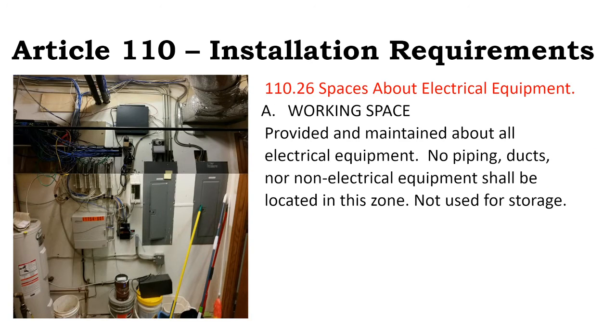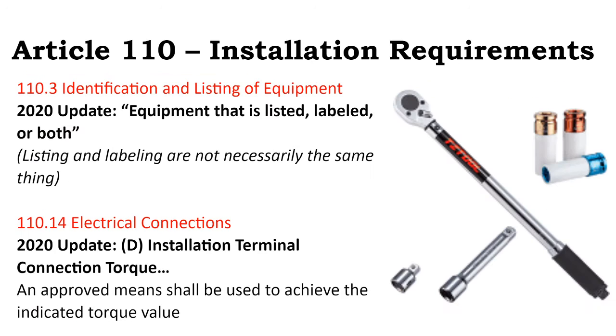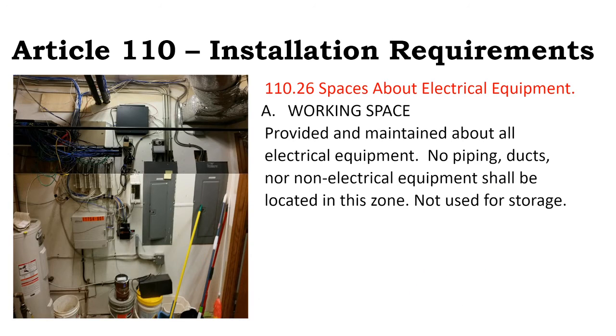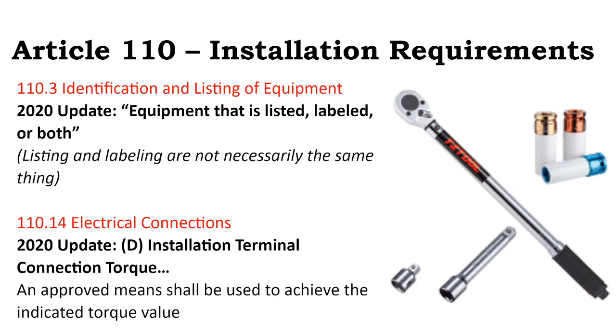Let's see. Torque wrenches nowadays are not that expensive. Finely precise ones or power tool activated ones are, but just the drill on its own, even if it has that screw setting for torque, it's not giving you a precise torque value. And with these electrical connections, you're building these power systems, it's no slouch. You don't want these connections to come apart and work themselves apart. You don't want to over tighten. You don't want to crack any terminal blocks.